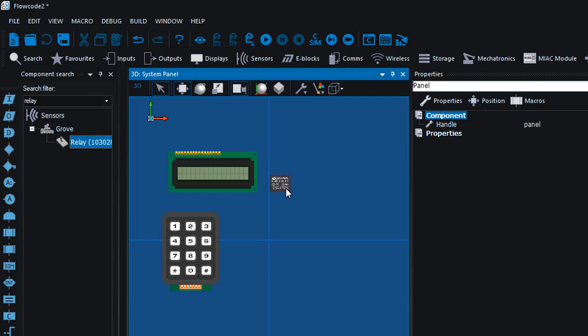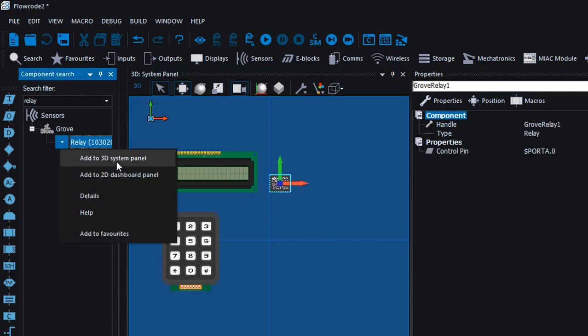A relay is basically a controlled digital device capable of switching much higher voltages and current than the normal microcontroller output pins. The maximum current for a single output pin of an Arduino is limited to 40 mA. Beyond this, you can start damaging your board. The Arduino board can source only a total of 200 mA. So if you want to switch high voltage and current, such as controlling a heater or a fan, you clearly cannot use the Arduino pins directly, as you could damage the Arduino. We're gonna use a relay. We're gonna need a second relay.